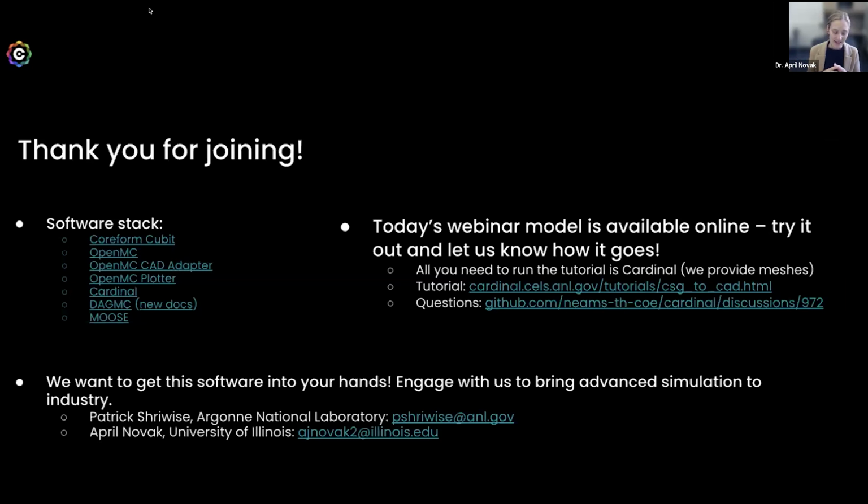In addition, Moose has a very wide array of applications which tackle some more nuclear specific use cases. Something that Moose has, which I don't believe ANSYS would have, would be all of the neutronics capabilities. Deterministic neutronics is in an application called Griffin, which you can apply for through the NCRC organization, or Cardinal if you wanted to do this with Monte Carlo neutronics. So some physics that are nuclear specific would not be in ANSYS.